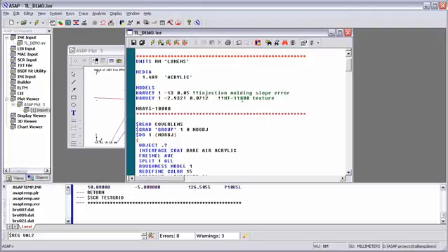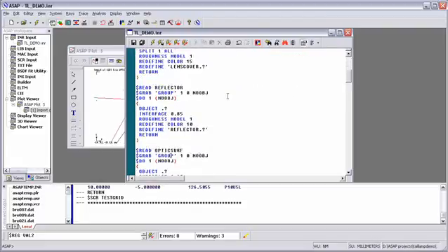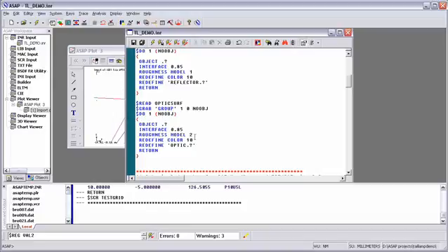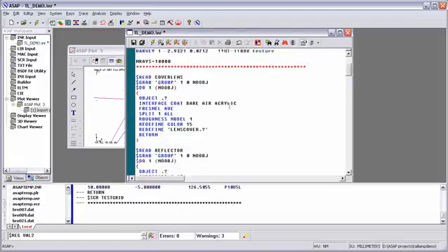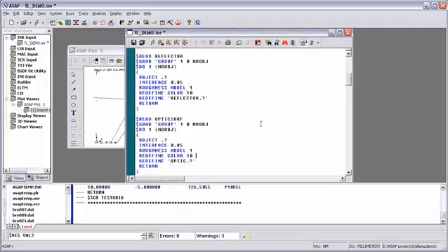The other thing that I've got set up in this particular file is a texture. For those of you that are familiar with injection molded parts, a lot of times they'll put on something called stipple or Mold-Tech finishes. And actually in this case, I've simulated that reflector using that texture. If I wanted to find out what the performance is without that texture, I simply have to change my model back to just the bare molded slope part, and I could rerun my simulation and have that result.